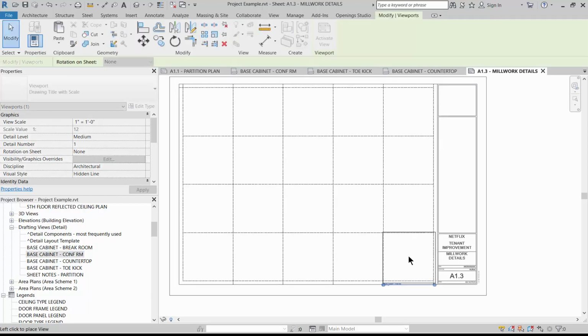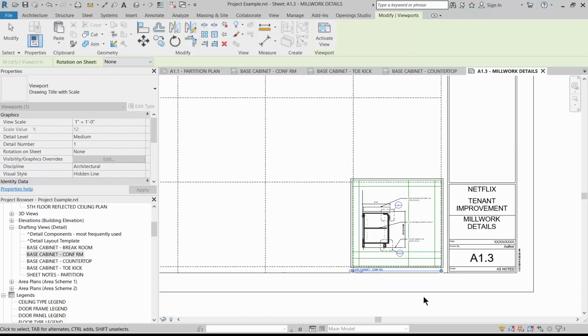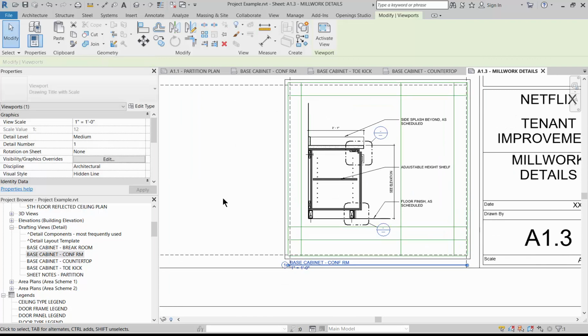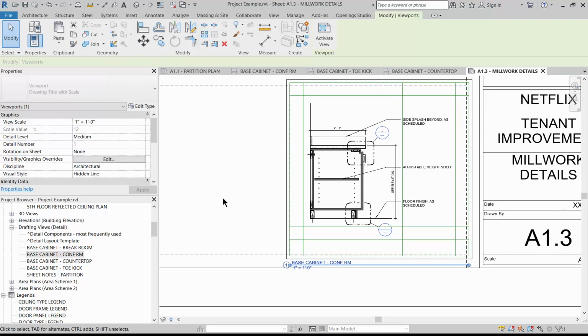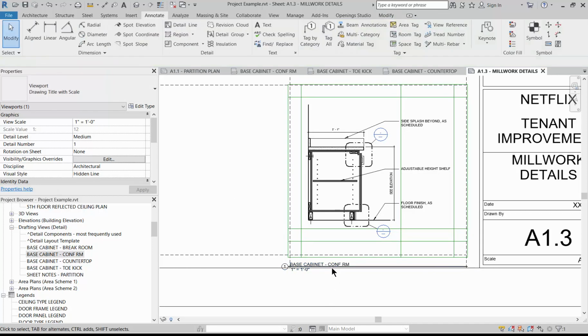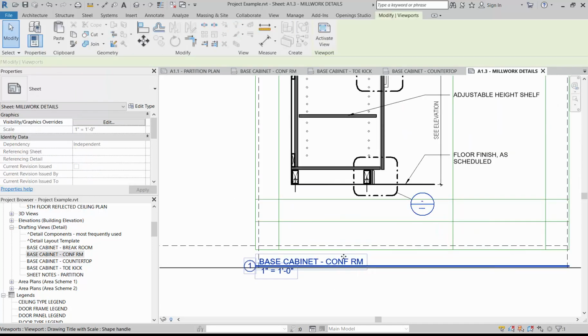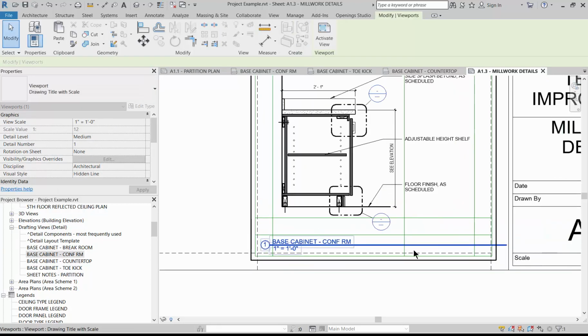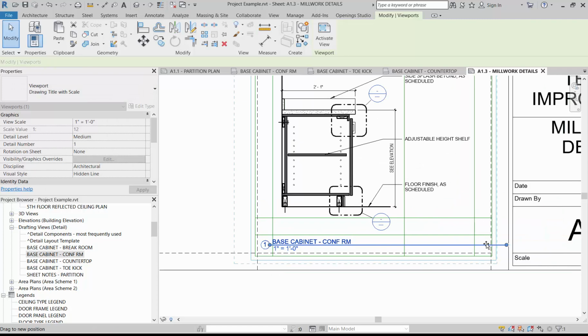And we usually start the numbering in a bottom right hand corner, sometimes top right hand corner. Both strategies are pretty common. And then make sure we align our border and the dash lines, and then the detail title goes into the bottom section of the detail that we created right here.